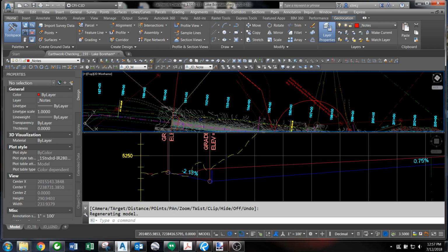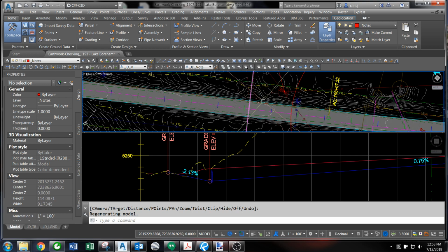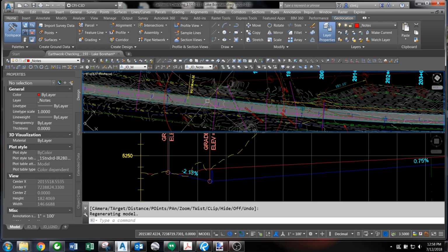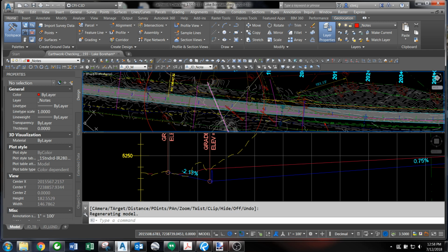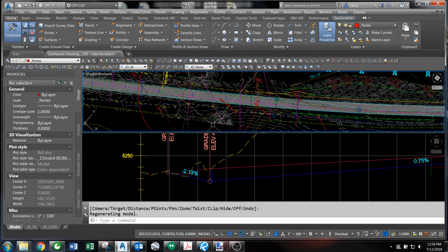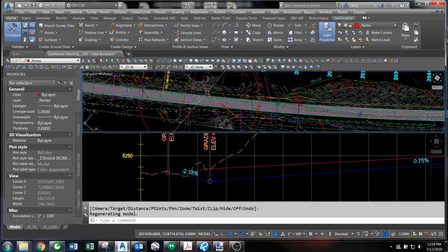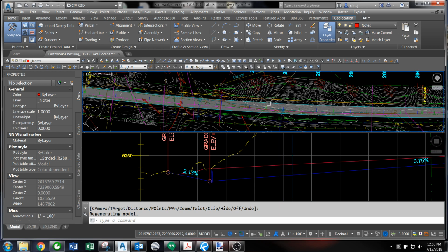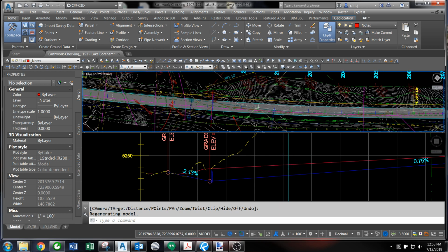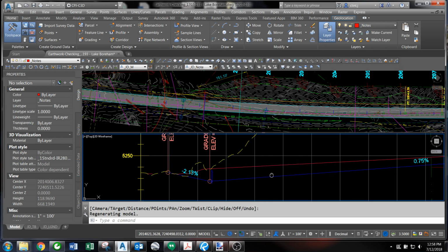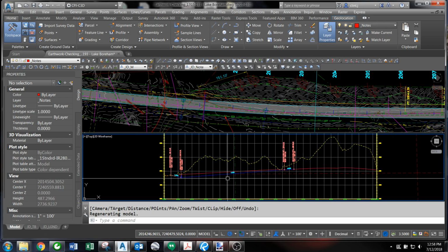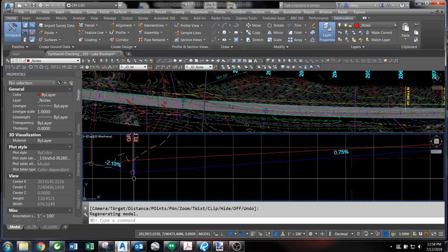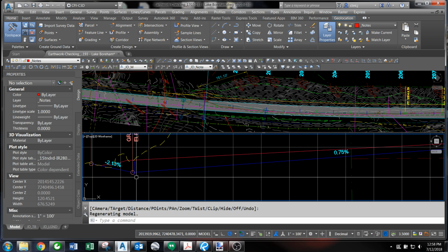So we come into the first area here where we're doing some construction. Here's the culvert we're not touching. I think it's a BIA culvert or something, but that's the big culvert. Once you get under that, you start to get into this cut on the northwest side of the road. You can see I ran this profile along our ditch to see how things were going, and we also needed to bury our culvert to get cover, to make it work.